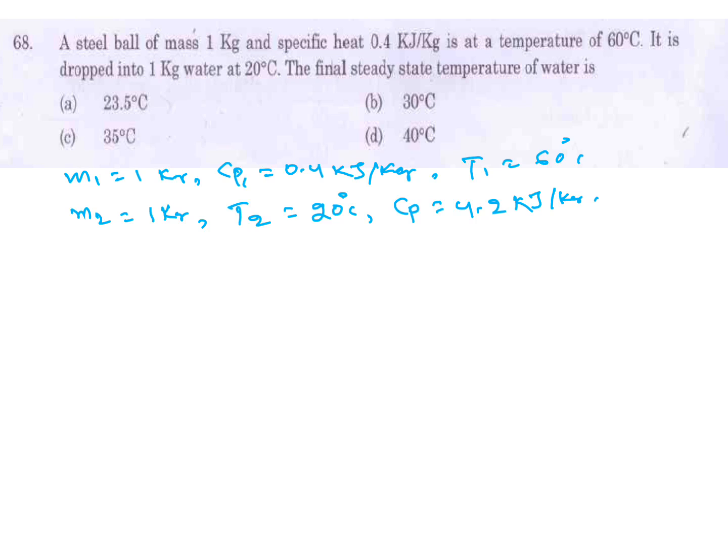So heat loss by hot fluid is equal to heat gain by cold fluid. M1 Cp1 into T1 minus final temperature equal to M2 Cp2 into Tf minus T2.